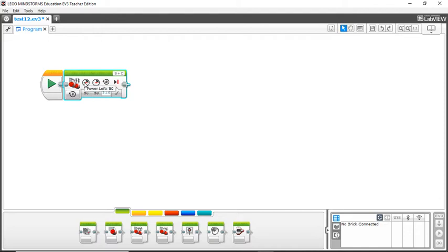These two boxes right here are each power, and they control each motor. This one controls B and this one controls C. Typically in FLL, if you're driving forward, you just want to drive at around 75% power, because if you drive at 100, sometimes you get some inconsistencies. So if you're just trying to drive forward, you can just type in the same power for both, and then however many rotations. If you want 2 rotations forward, there you go, 2 rotations at 75% power. They're matching, so you're going to get a straight line that your robot drives.